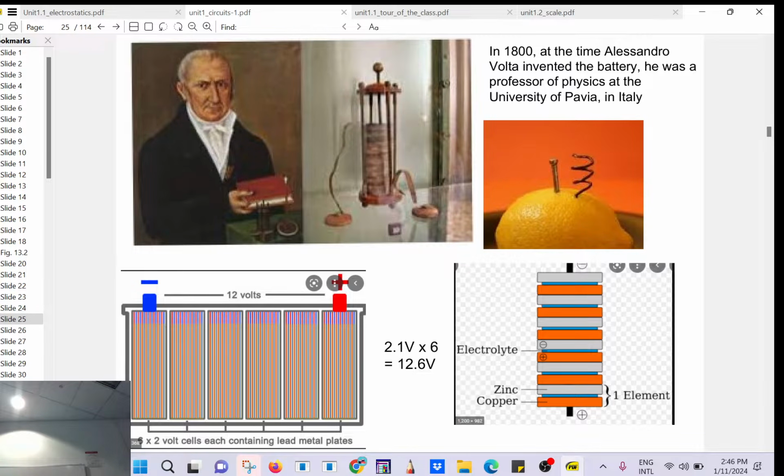So, do you remember what we said about the outlet? Alternating current, right? Not DC. How much voltage do you expect? 120 volts AC. So with my voltmeter, I can check this out, except that you have to put it in AC. You see, you have voltage for direct current, voltage for AC. And then in the outlet, you have